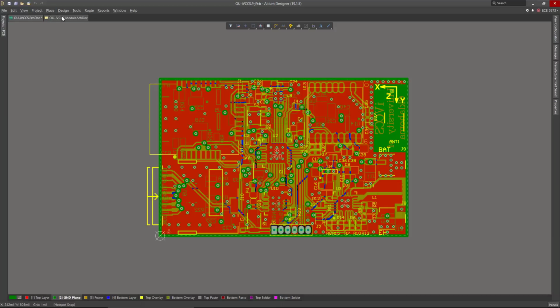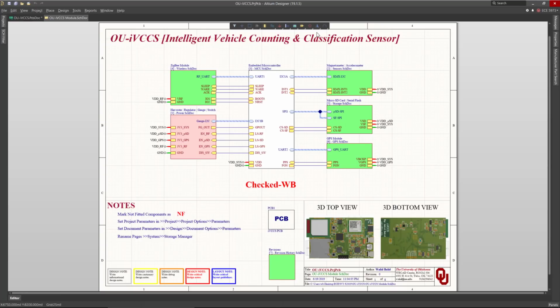Now if we go to the schematic, again we will see a different active bar. If you right click, you will see the other commands under the same button. Here all the power ports, you can see them in here. Here you can see all the different types of wires. We have wire, bus entry, net labels. We are going to use all of these, so no worries for now. Here we have different directives. This is the directive list, and here we have just text. Here we have regular shapes for drawing and so on.